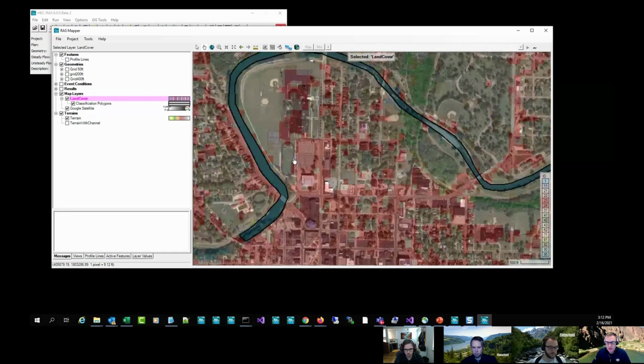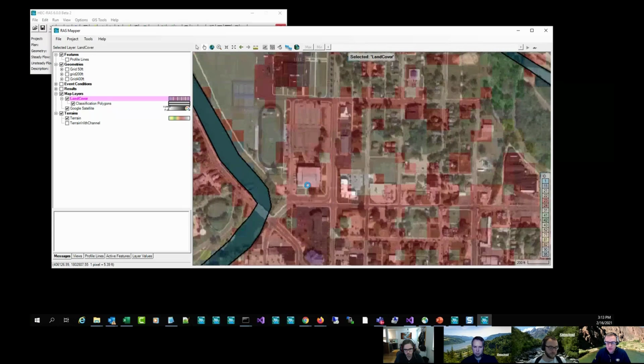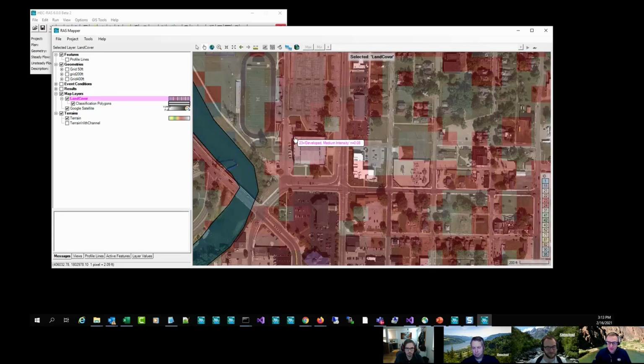So let's do something different. In this case, let's pretend this building is the basketball gym. It's been weatherproofed, stormproofed, so you're not going to have any flow through here. As we know, there are two different ways we can model areas where we expect to see high N values, like buildings. Typically we would recommend that when modeling a building, we'd want to use a high N value.